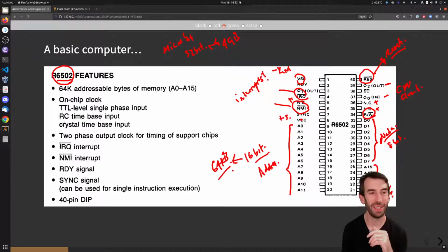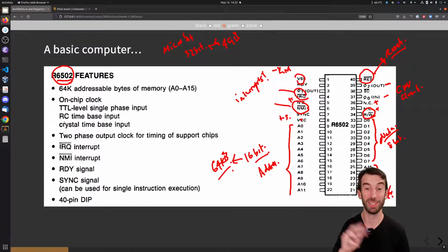Sorry if I'm wrong. And then the NVIC on the Cortex-M4 can have capacity for something like 400-something possible interrupts. Of course, they're not all there, but there's obviously that huge list of interrupt vectors in your startup script. And the 6502 has a total of 2 possible interrupts. I guess you can call reset an interrupt as well, but that's a pretty brutal one.